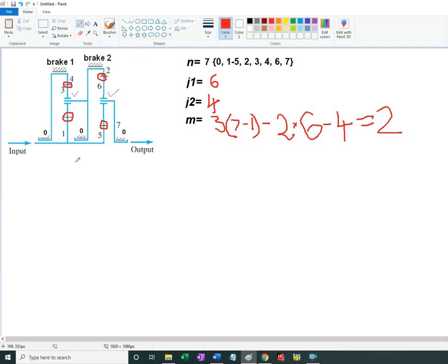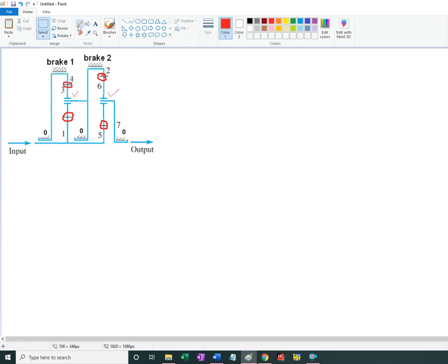That's omega input. So what I'm interested in ultimately is omega 1,5, that's the input link over omega 7. But before we can get this, I need to write two equations corresponding to the two planetary units in a motion inversion, that is, subtracting the omega of the carrier.